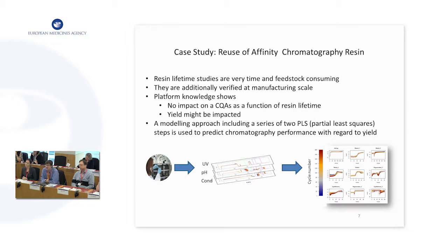So basically, we have small-scale data. We use the chromatograms of these small-scale data, different information in the chromatograms, and then we get what is called a multivariate batch evolution model. What you can see on the right side here. So this is not a chromatogram anymore. This is a multivariate representation of certain phases of the chromatography.